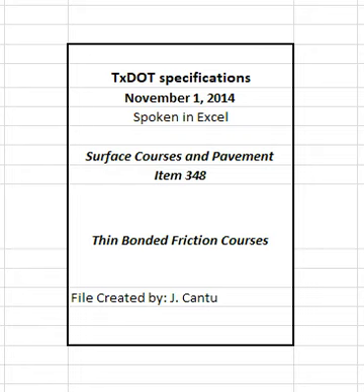The engineer may allow compaction with a light finish roller operated in static mode for pavement temperatures below 160 degrees Fahrenheit. Allow the compacted pavement to cool to 160 degrees Fahrenheit or lower before opening to traffic unless otherwise directed. Sprinkle the finished mat with water or lime water, when directed, to expedite opening the roadway to traffic.